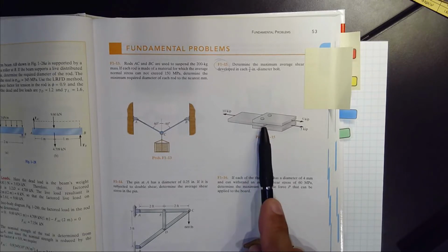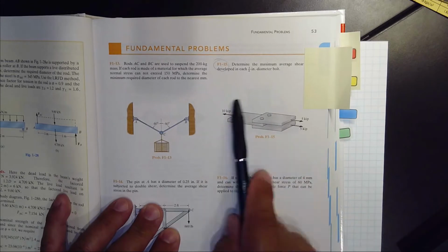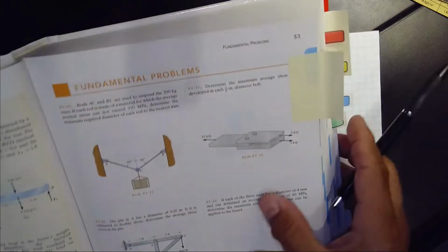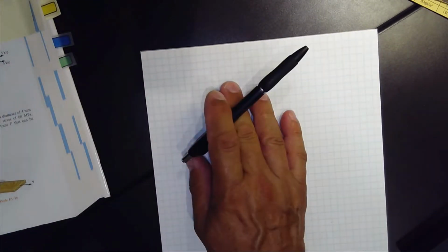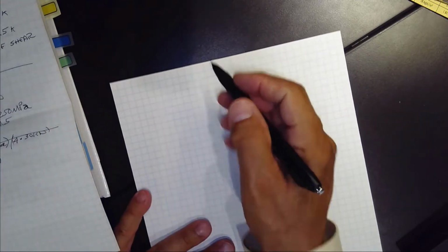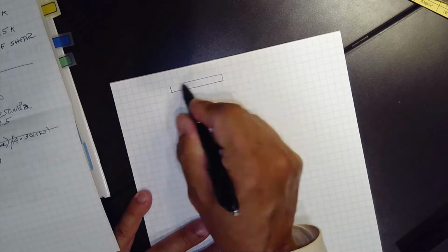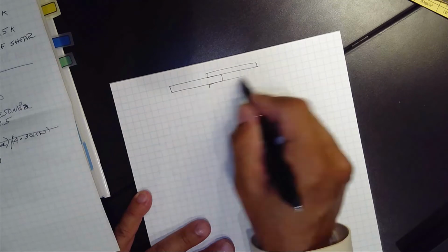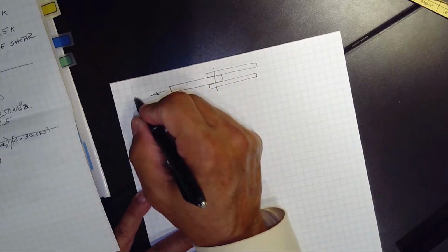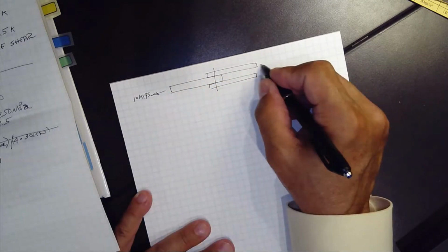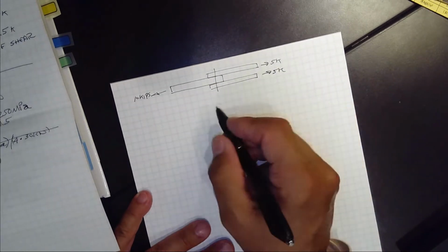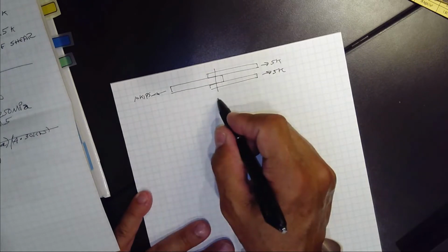So this is basically the free body diagram of the entire structure. We don't have to duplicate that. But let's do a free body diagram of the fastener. So as I said, we've got 1 plate here, another plate here, another one here. There's 2 fasteners. So even though we know that this total load is 10 kips, so there's 5 here and 5 here, because there's 2 fasteners, the load on each fastener is half that. So let's look at the one fastener in particular.